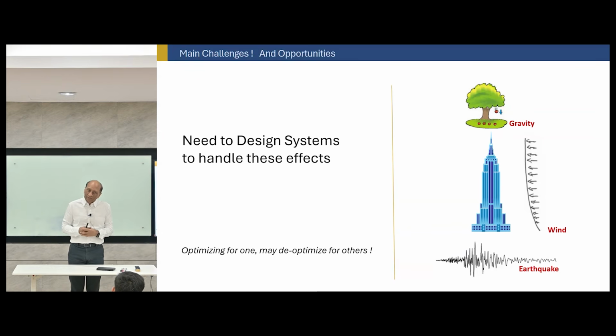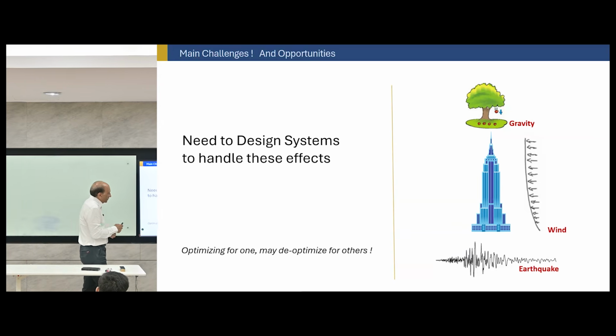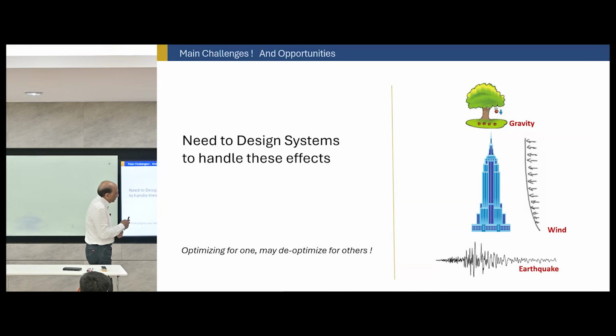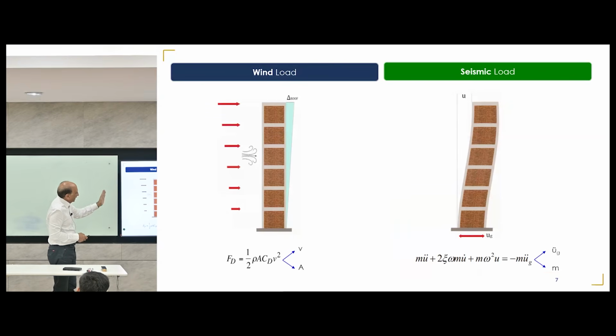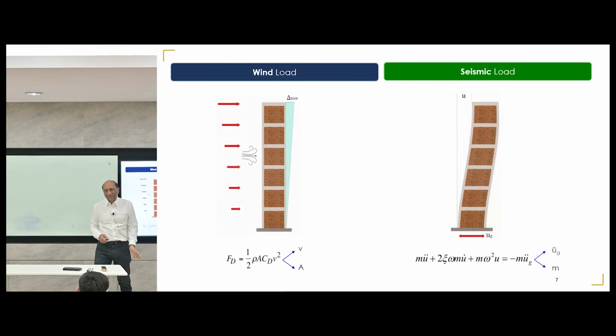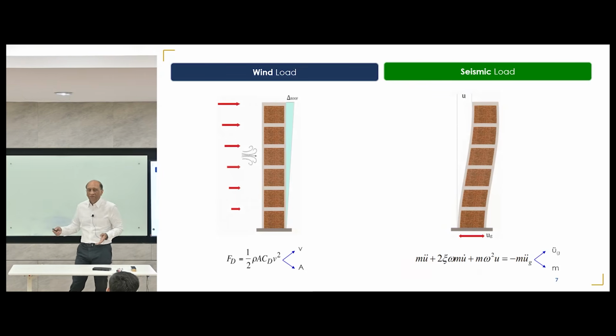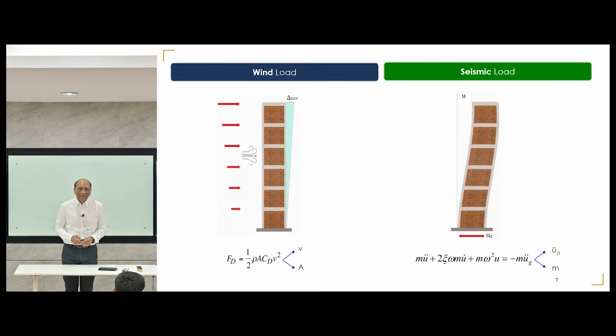It's not that complicated. But the lateral loads are very, very important, and they are complicated because of their nature. We talked about how wind load and earthquake loads are very different in nature. This one is a load, and that one is a displacement. So we now have to come back to how we are going to handle them in analysis.